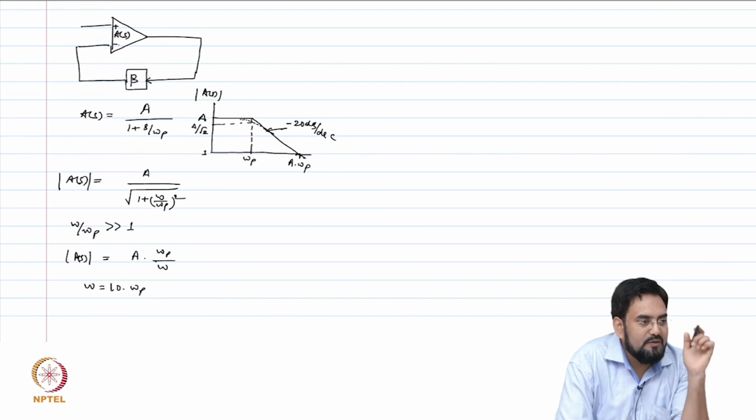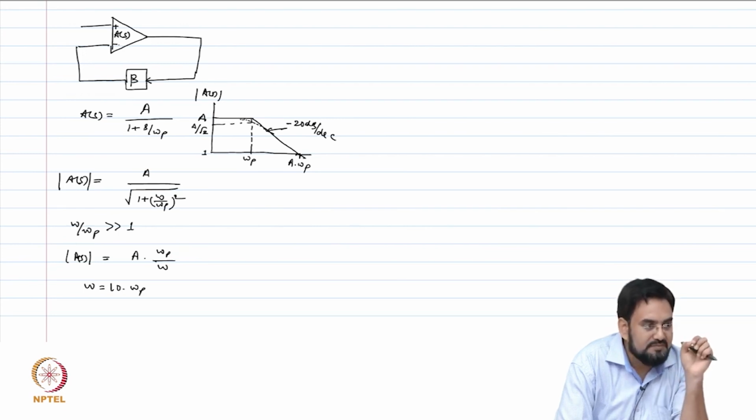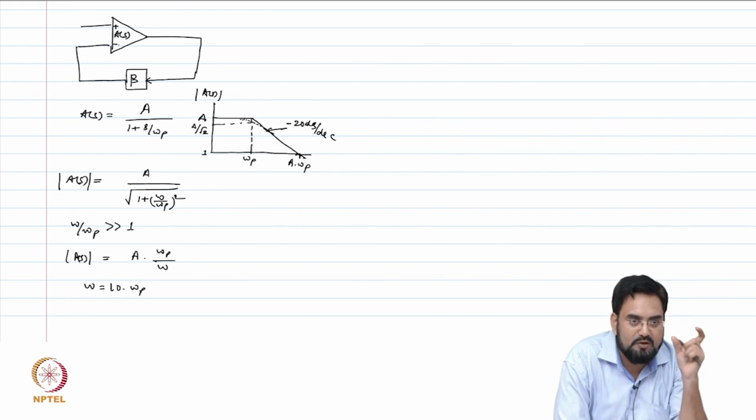Overall loop. By looking at the pole of the loop gain, can you just say that it's stable or unstable? You should look at the gain margin. Phase margin. No, not phase margin. I am looking at the pole location, left hand or right hand. So when you say left hand, right hand, that is defined for your closed loop, not the open loop. And when you define the phase margin, gain margin, that is for the open loop system, your loop gain. So there are two differences here.